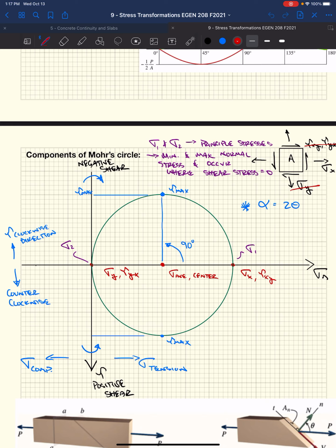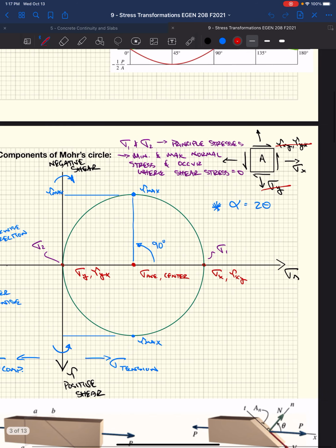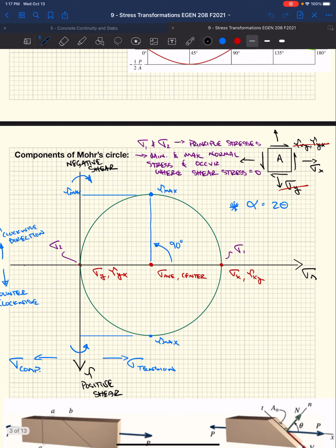We landed on our Mohr's circle, right, on the x-axis. And so if we rotate 90 degrees on Mohr's circle, we essentially would develop what our maximum shear stress is in that element, okay? And we could figure out what that stress state would be. So if we drew a block, and it was A again, and this A was at 45 degrees, if we were looking at the stresses on these faces, they would be our maximum shear stresses.